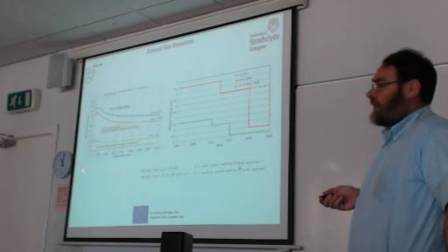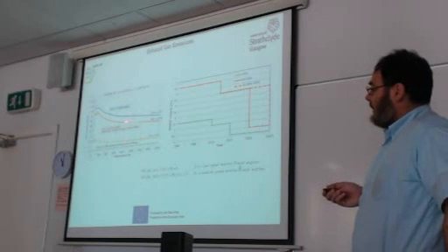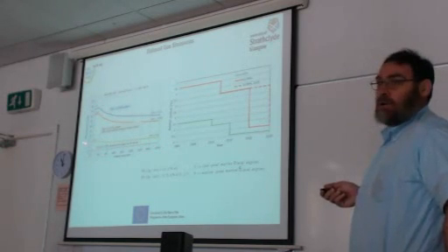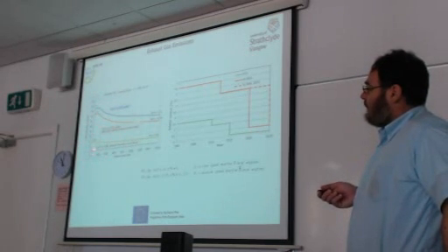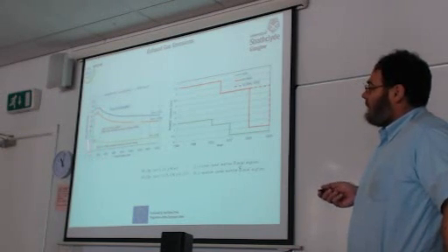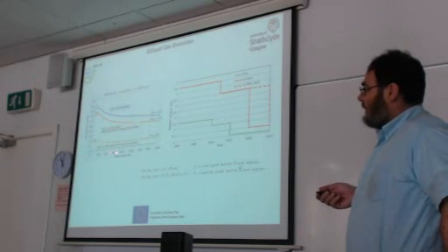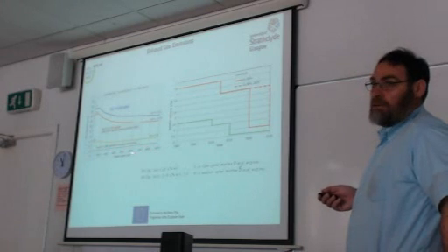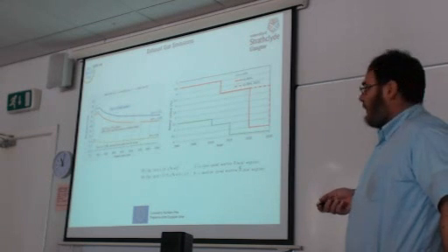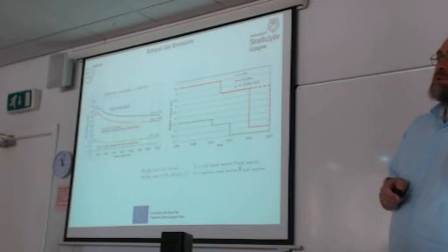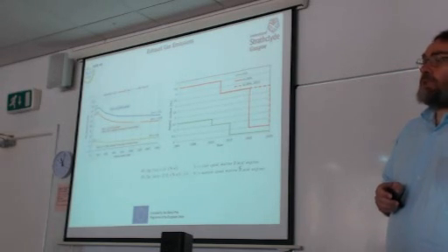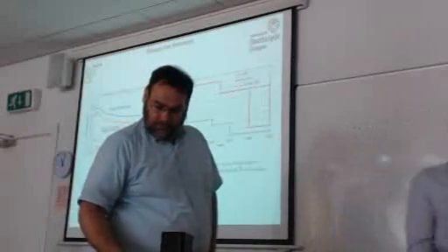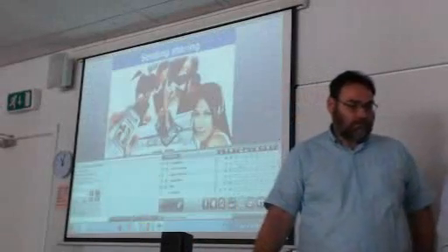Yes, that means that if I have a ship with one big two-stroke engine and another with two high-speed four-stroke engines, the regulations for the first ship are more flexible. Depends on the speed. No, they are not flexible. Depends on the engine speed. Always, as far as NOx emissions are concerned, the regulation depends on the rated engine speed. All the merchant ships operate with two-stroke engines below 150 RPM, so there is no differentiation here. Then it depends on the engine speed, but we need to remember that the higher the engine speed, the lower the efficiency. But this is another discussion.